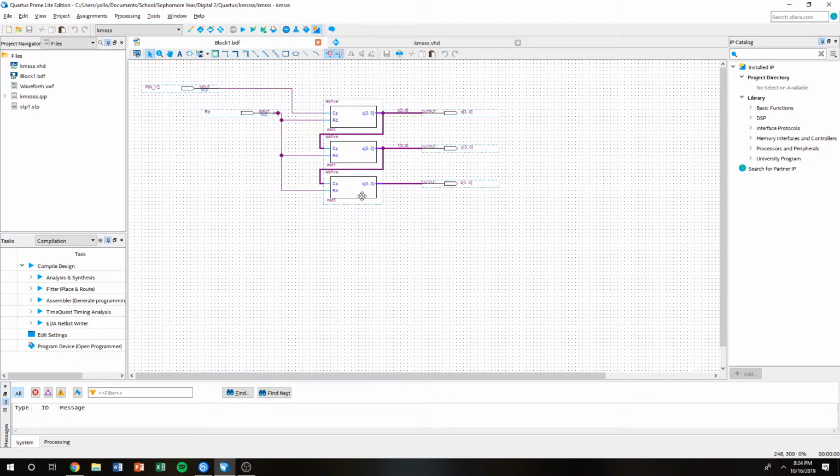Essentially you have 3 counter modules here, and when the most significant bit of this module is high, then it will count up when it falls down for this counter module. And then for the next counter module, it's the most significant bit of this counter module. If you want to, you can make it more digits, or you could just make it 2 digits. For this tutorial, we'll be using 3, and we'll be showing the outputs of this in SignalTap.